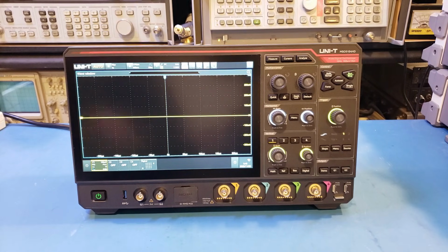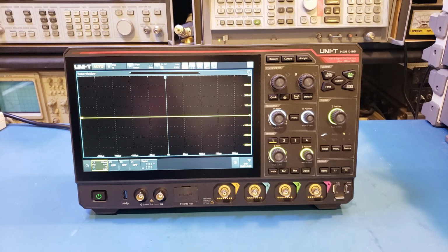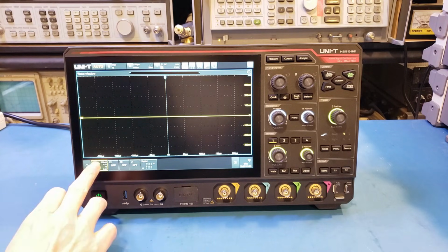Next, let's take a look at the 1 GHz bandwidth. Of course, as a lab-grade instrument, I have no doubt of the claimed bandwidth. But what I wanted to see is how the waveform looks at the bandwidth limit and how much margin we actually have with the bandwidth. For this test, I'm going to hook up my HP8642B in the background in a moment, which can generate sinusoidals up to 2 GHz. Let's first change the channel input impedance so that we can match the 50 ohm as expected by the 8642B. So to do that, let's come to the channel.